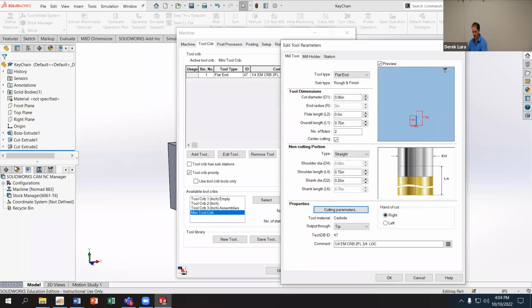That's something I didn't really talk about, but the machine will specify cutting speeds based off of the tool type as well as the material type. So it is figuring out what kind of feed rate is appropriate based off of the horsepower of your machine, the strength and elasticity of your base material, your workpiece, as well as the hardness and some of the properties in terms of the diameter and things like that of the tool.